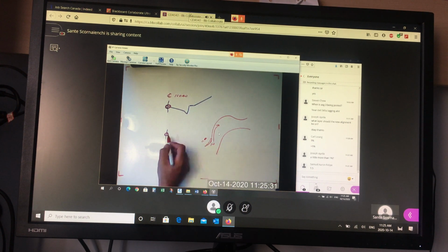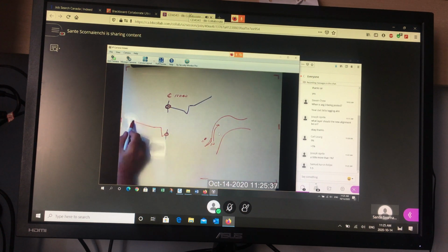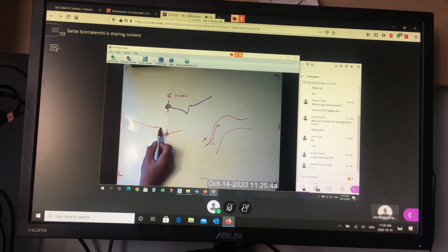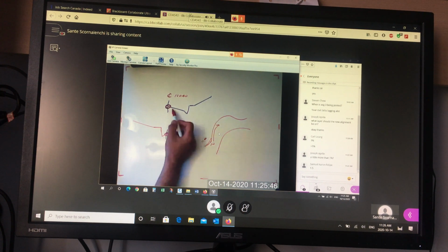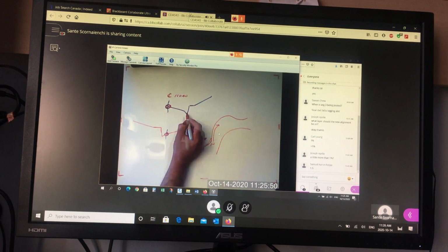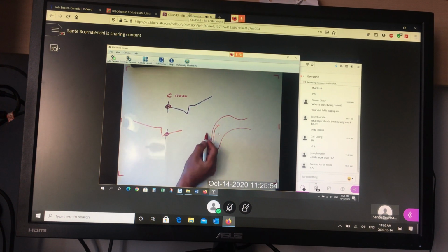So with respect to this, I want to go down to the gutter, up the face, across to the back, and over to the street line. And on this side, I want to go to the center line of the road. So I've got 1, 2, 3, 4, 5 pieces, just like I have here. But the reference point is not the crown of the road, it's the gutter point. And it's the left side, right? I want the boulevard on this side, not this side. Remember, positive change in this direction, I have to build these pieces.